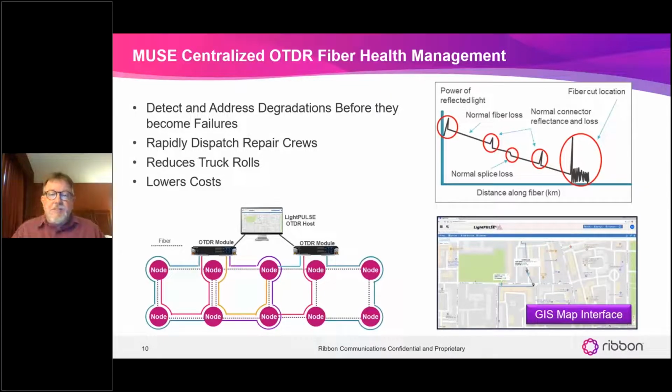It works by sending signals out over the fiber, as any OTDR does, and then providing a trace, very much like the cartoon you see here in the upper right. This is a cartoon. OTDR splices look a little different than this, but after you've spliced it, obviously you can shoot another OTDR trace and then find out how much was that splice loss, right? Is it good enough, or do they need to redo it, right? So really a valuable tool. Again, it goes in place and in service from day one.